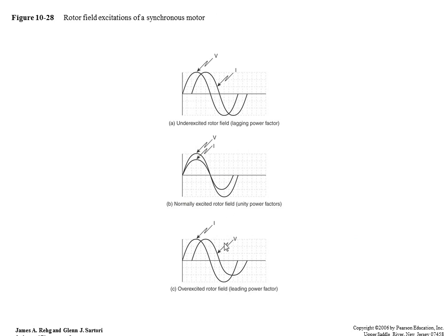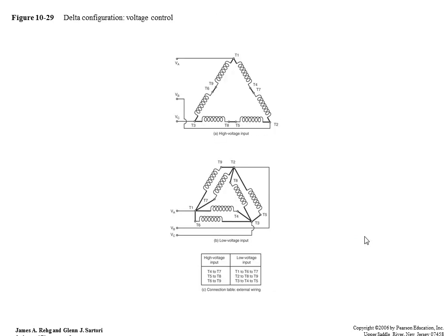Synchronous motor stuff. Rotating field, exciting in a synchronous motor. Okay, so same type of thing. Delta connected voltages, high voltage on top, low voltage on the bottom. The motor's going to have associated with it a wiring chart. So you're not memorizing this. It's not going to change. You could memorize this. But the day you take your memorization and hook it up to the motor is the day you did it wrong. Make sure you look at the chart on the motor as you're wiring it.